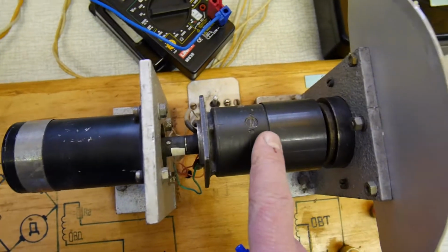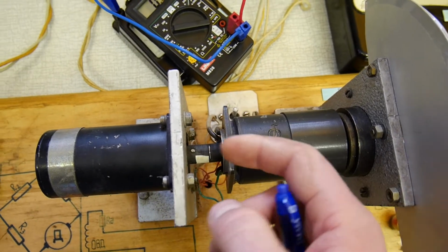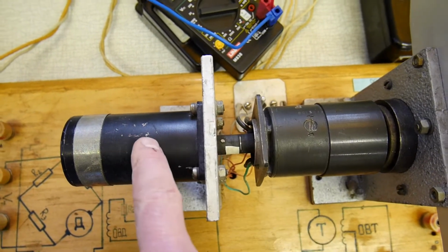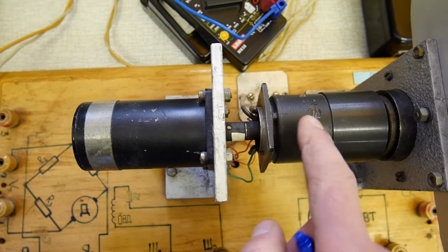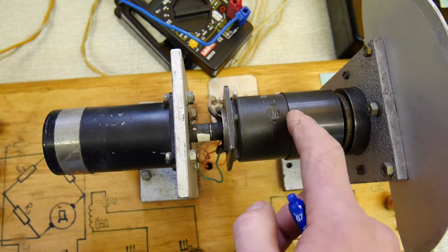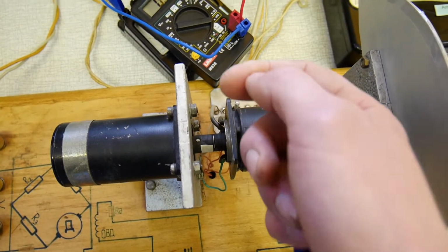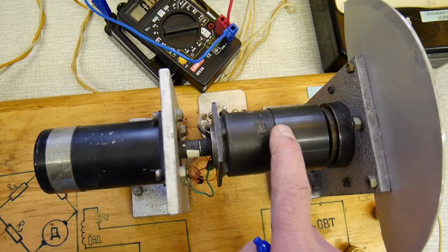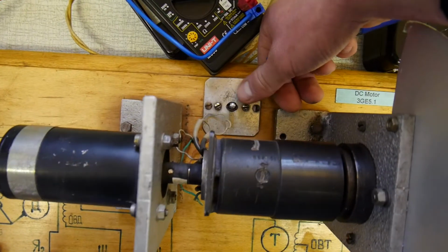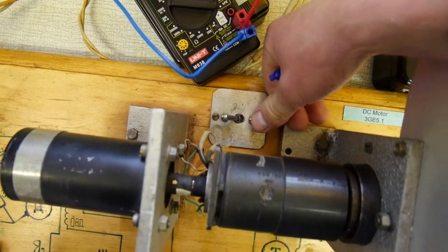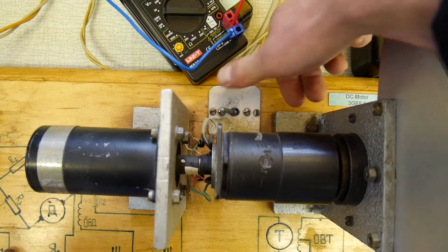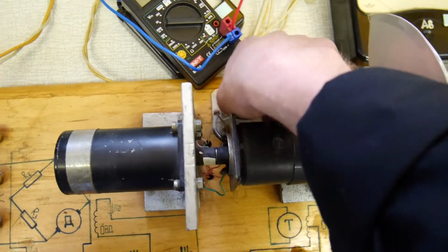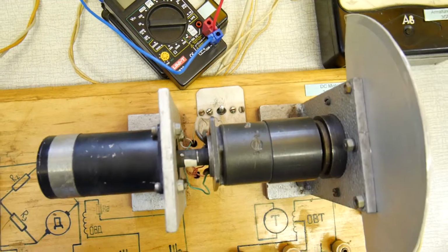If this machine rotates in the same direction as our DC machine, then it will accelerate our machine which is under test. However, if this braking machine tends to rotate in the opposite direction with respect to our machine, then this will cause braking. I can switch between these modes, so I can brake, or I can also add some speed to this motor. Now it is in neutral position.